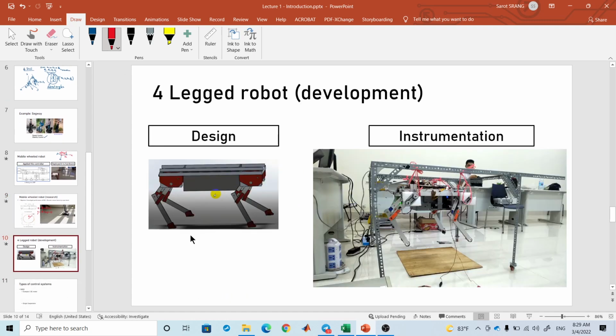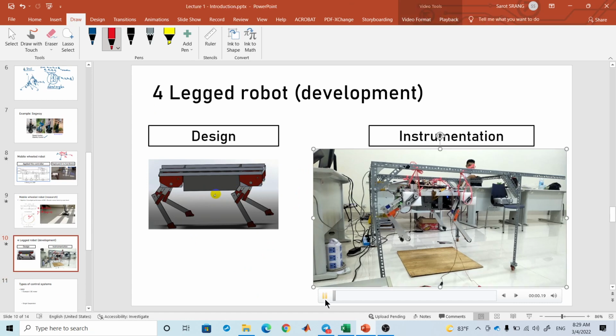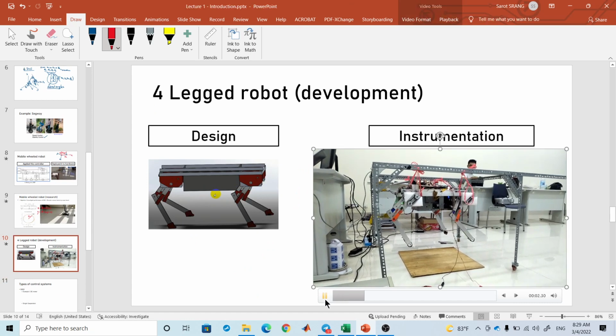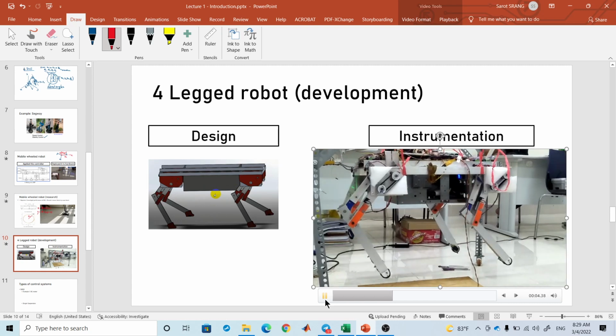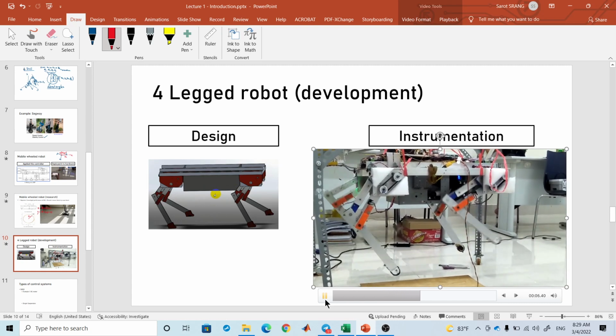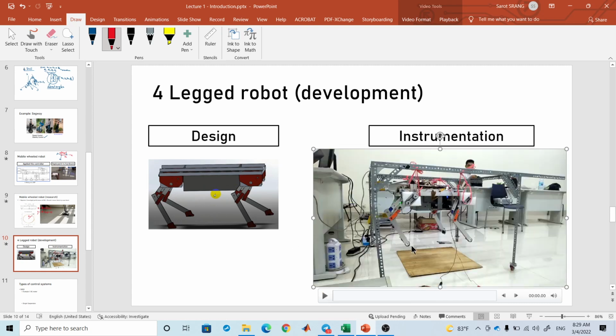Similarly in this application, from kinematics, if you want the trajectory of each leg here like this at a certain velocity, we compute the velocity of each joint, and then we control each motor to have such velocity. Okay.